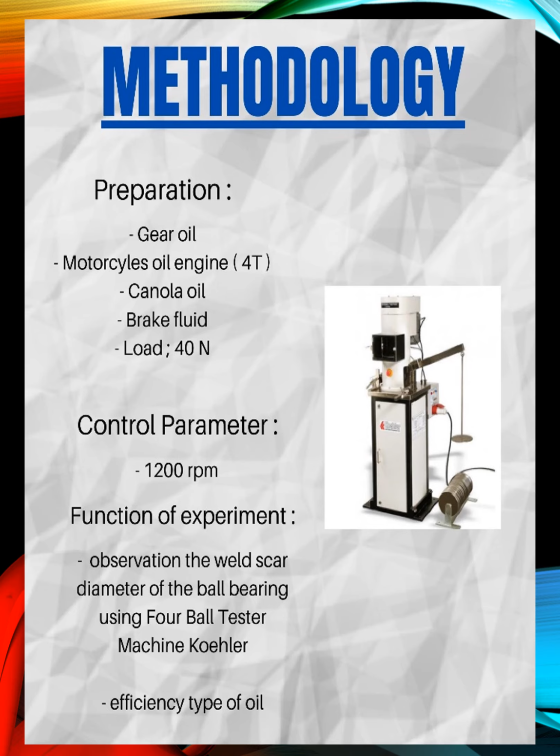Okay, sir, I will explain the procedure using that machine. First, clean the parts and the ball bearings of residual oil and grease using hexane. Second, place the ball pot disc into the ball pot. Next, place three clean ball bearings into the ball pot assembly. Insert the ball pot lock ring into the ball pot assembly. The ball pot lock ring is hexagonal in shape.